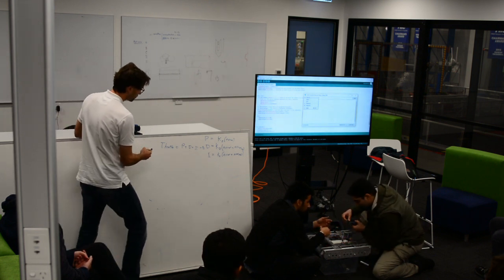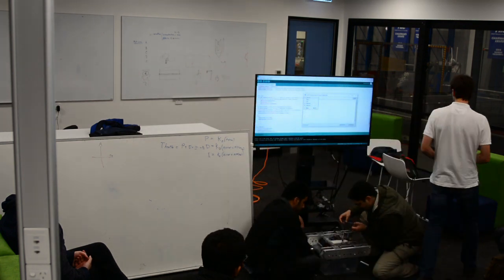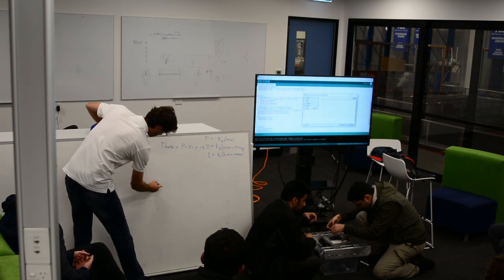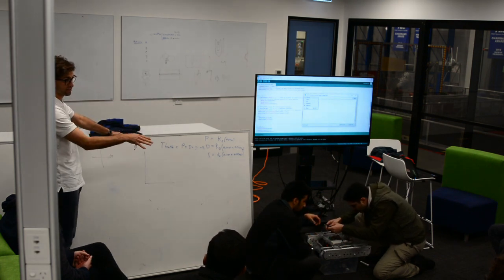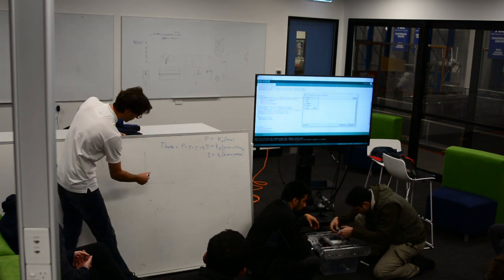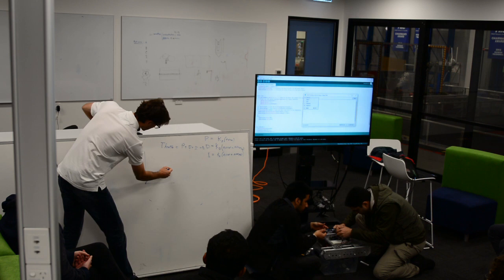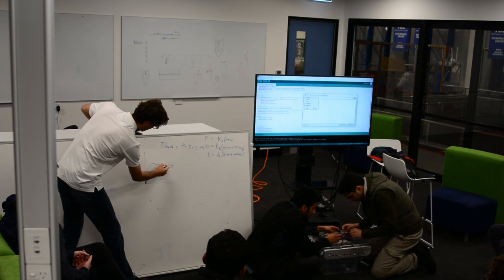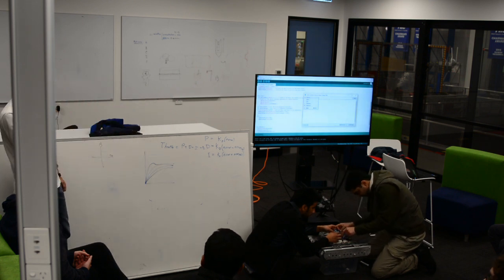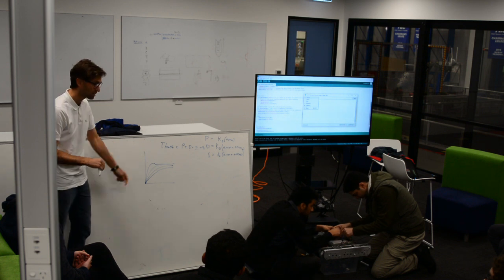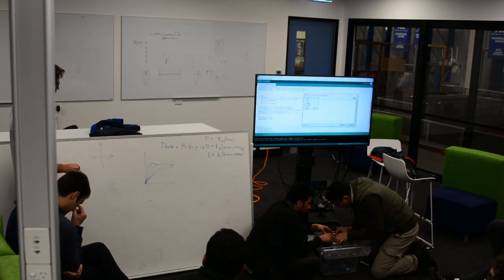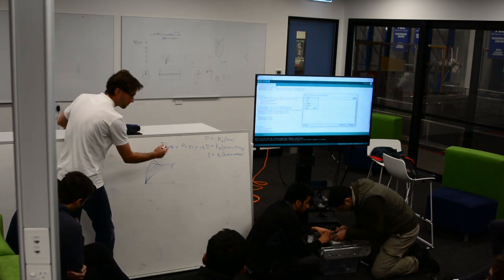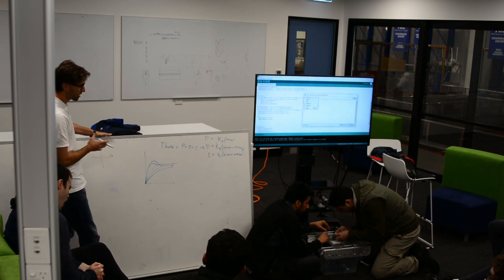And so if we go back to, I'll do it this way. If you want to tune a PID controller, you're looking at your step response. We've been looking at step response, right? And if you plotted the step response for most of what we're doing, we've been seeing things that look like this. That, or maybe that, or maybe we just started to see a little bit of that when we overshot just a little bit, right? We hit 101 or 1001 a couple of times, so we just started to get our P term large enough to get some overshoot. I would continue to increase that P term until we get a little bit more overshoot, and maybe even some undershoot on the back, but we'll see. You might not be able to get it because there's so much friction on this.